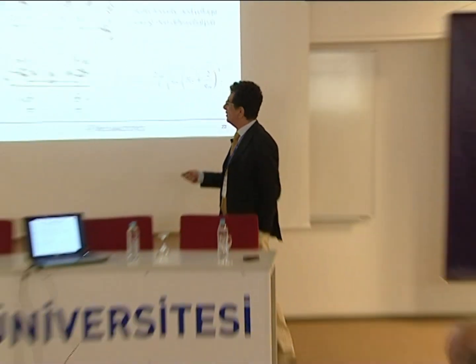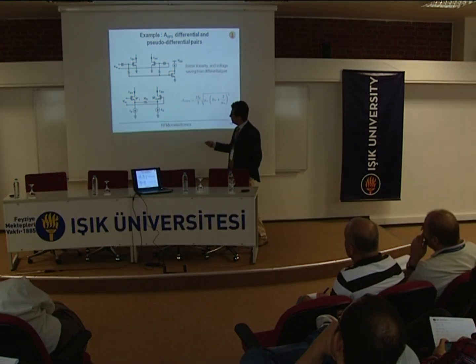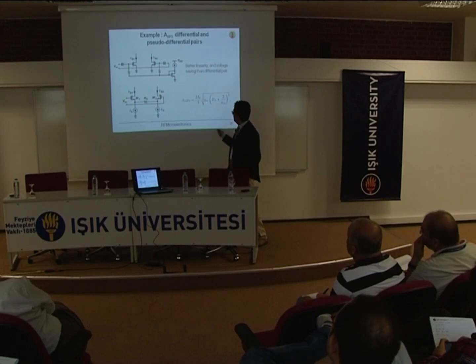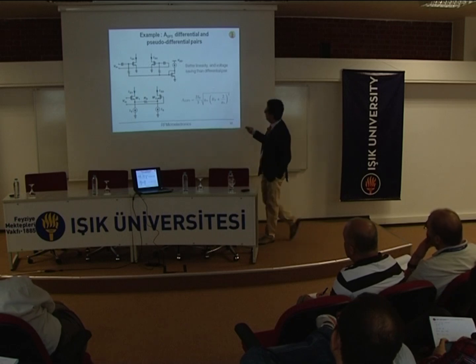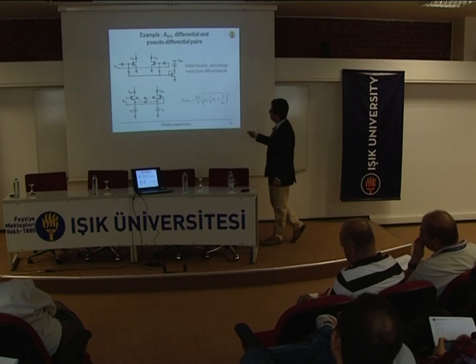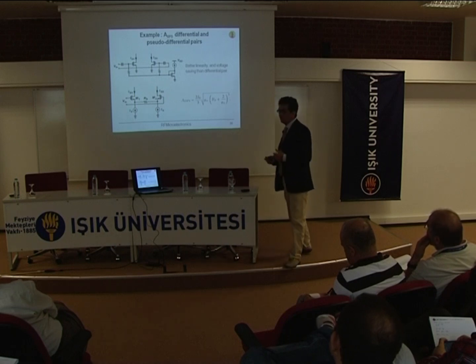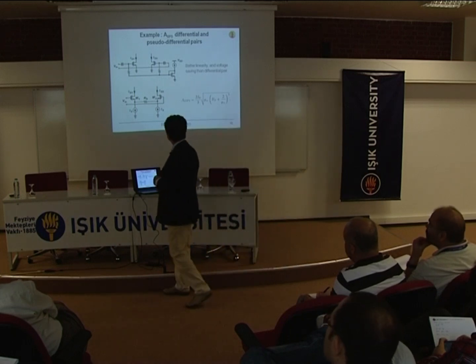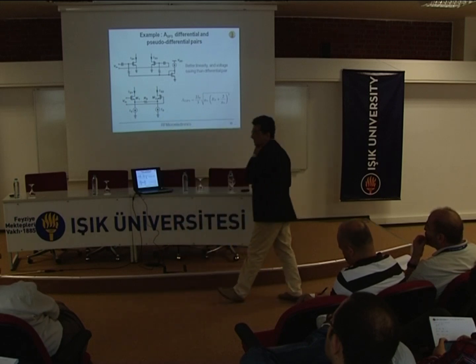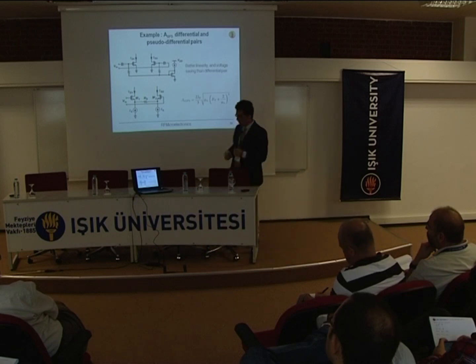Okay, so one way, for example, to improve the linearity of a differential pair is introducing a resistor. There are many ways to do it, so I wouldn't even say that this is the most common. Again, as an example, if we put a resistor between the two sources, then we improve the linearity of the differential pair, and the expression corrected by the presence of Rs is given by this equation. So, of course, it's intuitive: the more Rs, the better it is in terms of IIP3. The concept is different from having the sources at ground. Yes, it's different, you know, the linearity because you have the linear element. Yes, it's different.